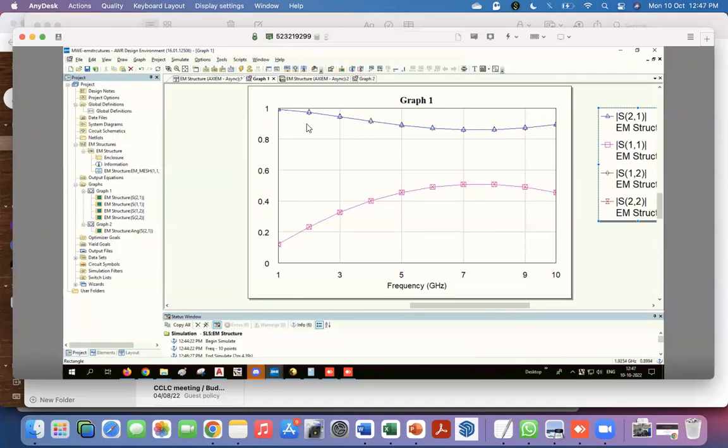But you again see that effect that at very low frequencies, these kind of mismatches have very little effect, because effectively the length of the transmission line is too short to have any transmission line type of effects here. And they start kicking in at higher frequencies, where the transmission is now no longer close to unity. The reflection is coming up as well. So this seems to be working.